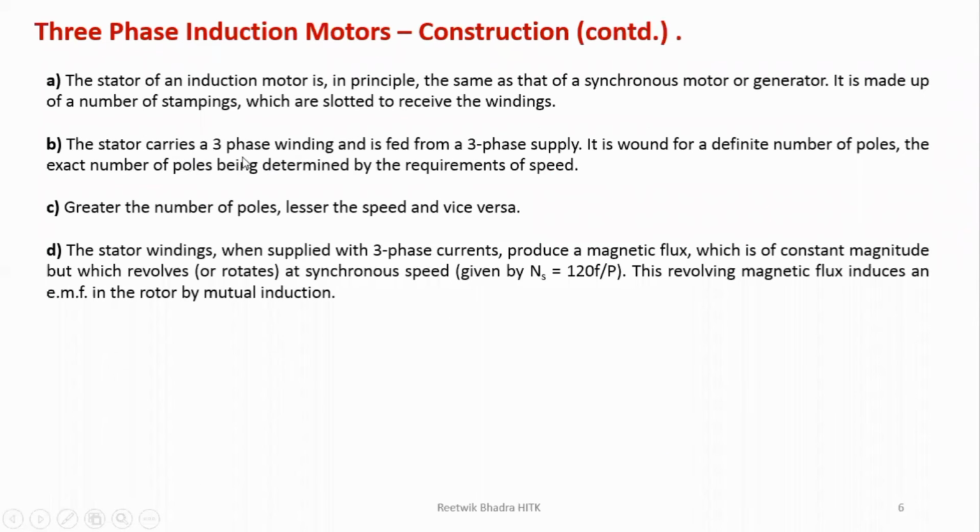Now, the stator carries three-phase winding and is fed from a three-phase supply. Yes, because it is a three-phase induction motor, we need to have three-phase winding which has to be given three-phase supply. It is wound for a definite number of poles, P is 2, 4, 6, 8, whatever it may be. It depends, and the number of poles will affect your speed also. We'll look into how pole and speed are dependent in later classes.